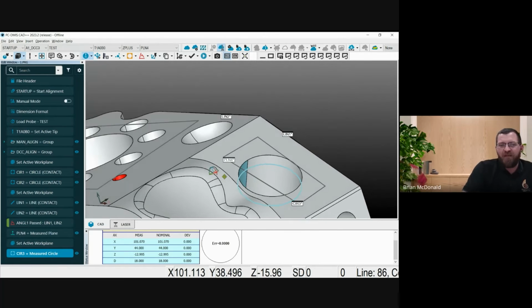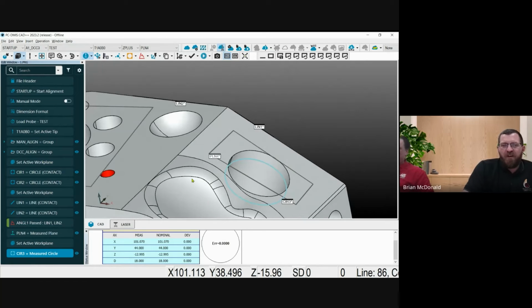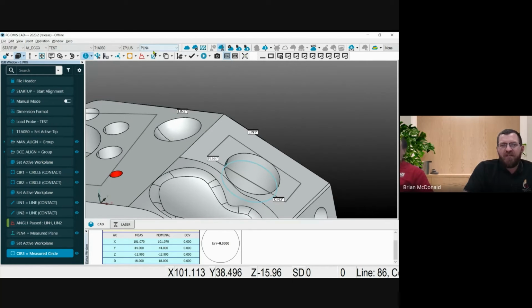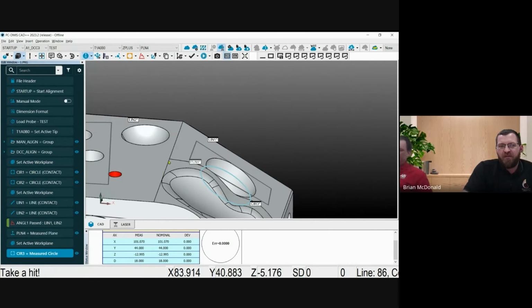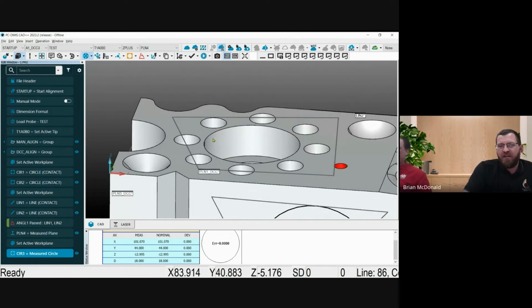Again, that's because I'm from a CAD model, but on your part, you will see something that should represent a reasonable error. So this is important no matter what you're measuring with of using that projection plane. It's extremely important when measuring with a portable device, like an arm. That's because no matter how good we're trying to take our measurements, those points are always going to move up and down. Whether it's in the Z-axis, X or Y, no matter where I take my points here.